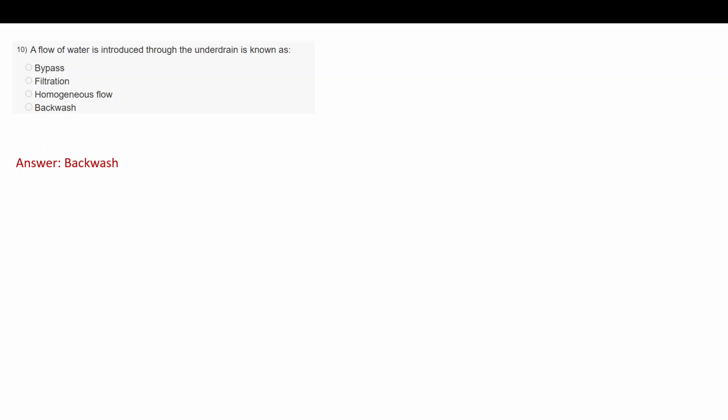Yeah, so backwash is usually provided by flowing water, usually in counter current mode, where the bed is allowed to expand so that any suspended particles or solids that are stuck will be washed away, right? So if the bed is expanding, suspended particles will also be washed away by that water. So backwash is important.